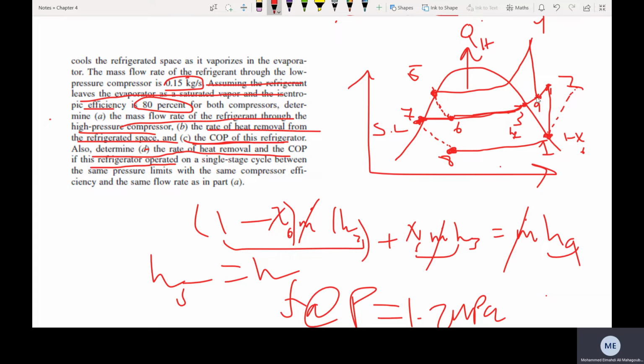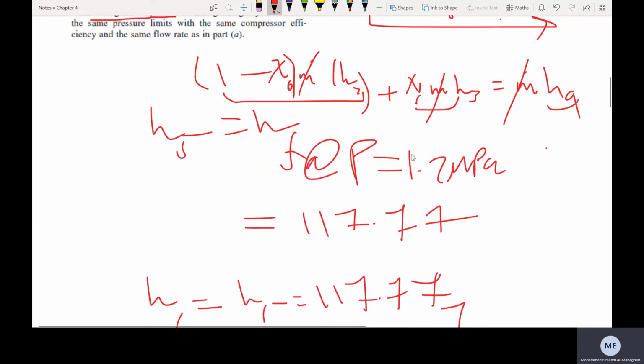And then from h9, you're going to make an isentropic process until point 4. So make the entropy constant, and you know the pressure here. And the pressure here is the same, because we are only having a mixing process.